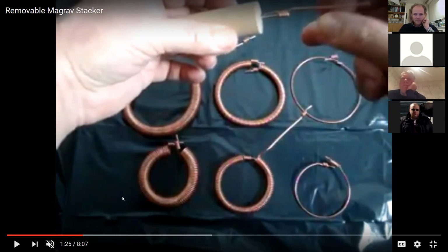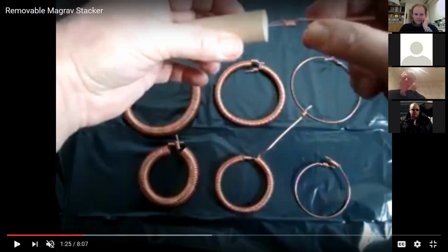Yes, find your own material. There's no recipe for it. So you have to match the diameter somehow with the diameter of the wire we use. If I'm using this 1.5 square millimeter wire, which is a Europe standard, this is 1.38 millimeters. For that, I found a 1.4 millimeter screwdriver. It works well. And also here he has, maybe you cannot see, a hole drilled in parallel into which he can put this end of the wire so he can twist it easier.